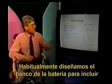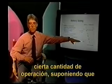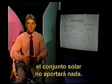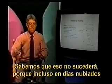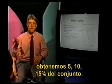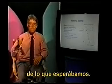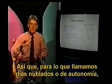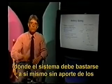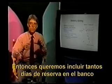We typically size the battery bank to build in a number of days of operation, assuming no input at all from the solar array. Now, that's not going to happen. Even on overcast days, we get maybe 5, 10, 15% from the array. But that's very low. We've lost 80 to 90% of what we expected. So for what we call cloudy days, or days of autonomy, where the system has to stand alone with no input from the solar modules, let's consider no input at all from the solar array.